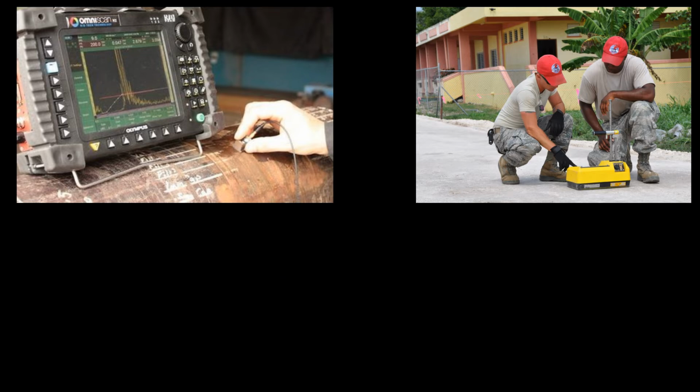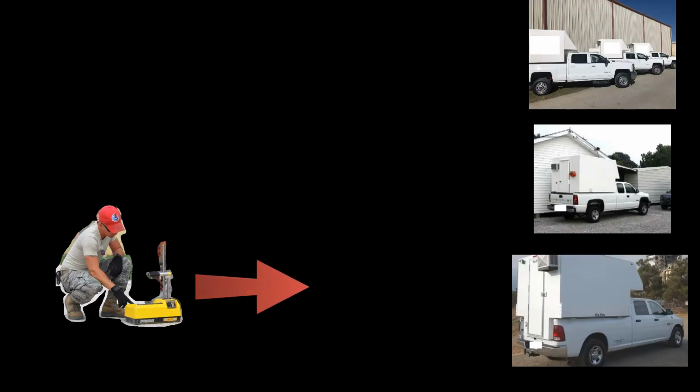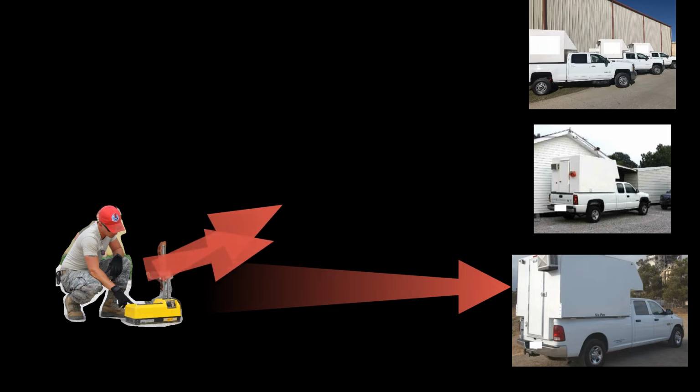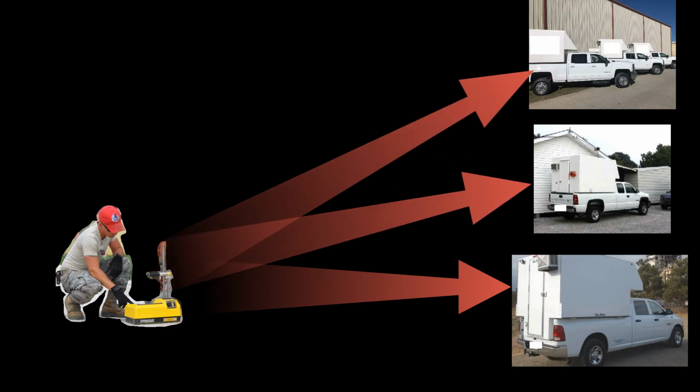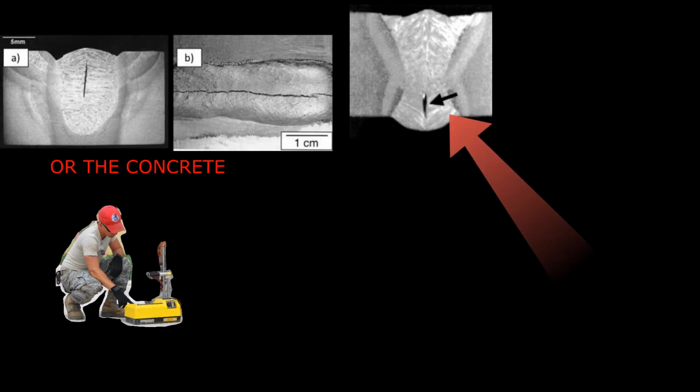What'll happen is that tech will take his machine and he'll go into this truck. If you see these trucks on the job site, this is where most of our radioactive situation is happening. He'll take that digital information to this truck, and he'll produce X-rays. He'll literally produce X-rays of the welds. And he'll immediately give the customer the X-rays, the physical proof of the non-destructive testing that was just performed. There's a lot of companies that'll take the non-destructive testing data and do the X-rays somewhere else.